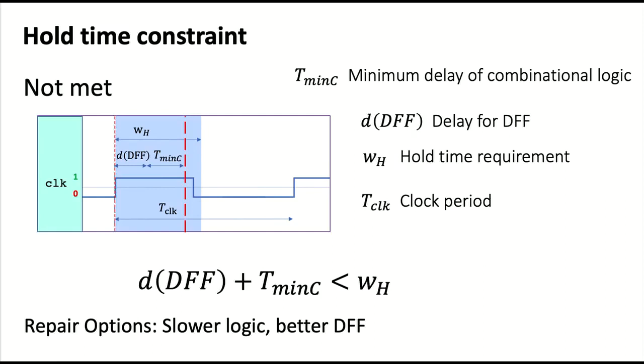Okay. All right, so those are the two constraints. Again, if we give you two values, you can figure out what the third needs to be, or what the constraint is on the third, right? All right, so let's talk about slack, because in lab 6, you're going to run a timing report, and it's going to report slack. It's not going to report delay. It's going to tell you how much slack you have. Okay, and so what does it mean?